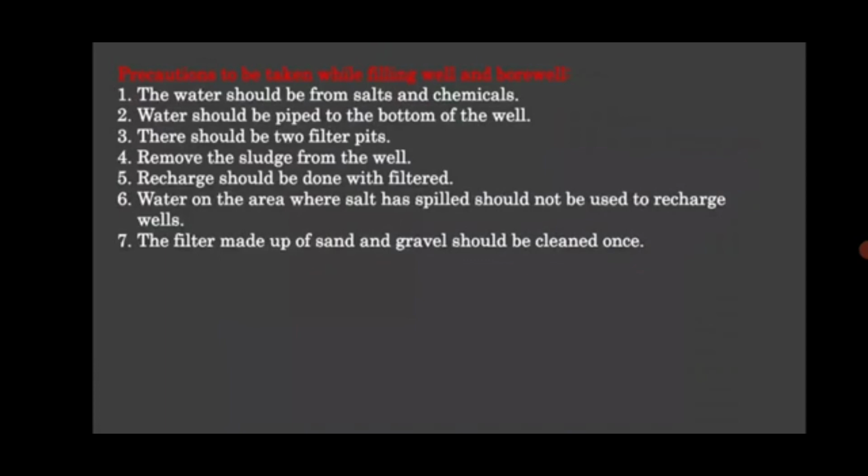The next, precautions to be taken while filling well and borewell. The first is, the water which is coming from the stream should be free of salt and other chemicals. Then water should be piped to the bottom of the well. Third one, there should be 2 filter pits before refilling. Fourth, whatever dirt or impurities are there, it should be removed from the well before refilling the well. Then next, recharge should be done with filtered and clean water only.